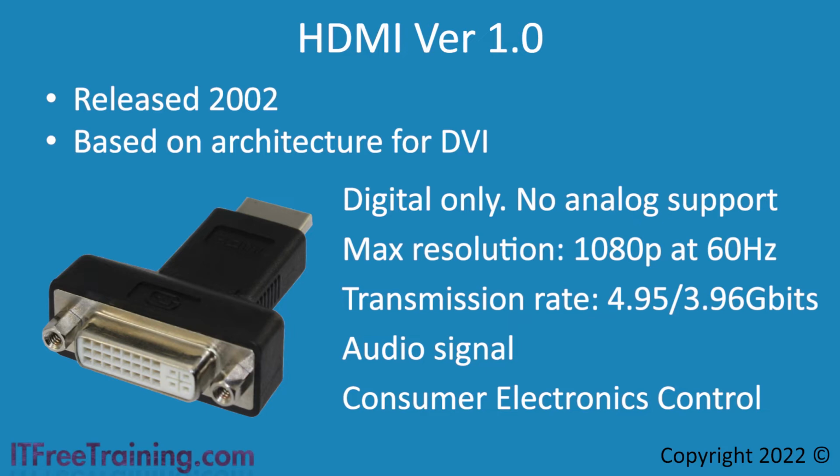This sounds like a great feature, however, there are some problems with it. First, each manufacturer is free to implement it in different ways and may call it different names. CEC is an optional specification for HDMI, so the manufacturer does not need to implement it to be considered HDMI compliant.